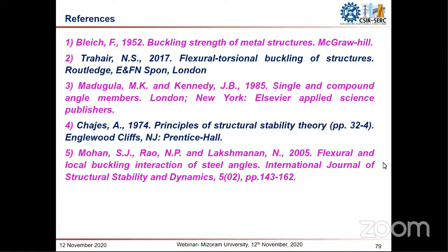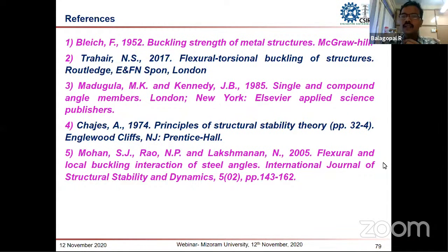Okay, sir. So normally in the tower testing research stations, will you include parameters like thermal stresses, or only the normal conventional load parameters? No. That will be converted into whatever the temperature effects are. Including the temperature effects, they will calculate the loads. Those loads will be simulated. We will not simulate the temperature stresses. Whatever temperature stresses have been taken into account while calculating the loads on the towers, those loads we will simulate here.